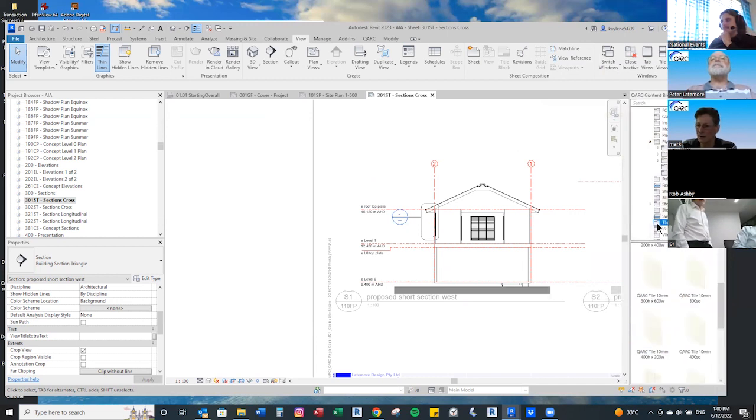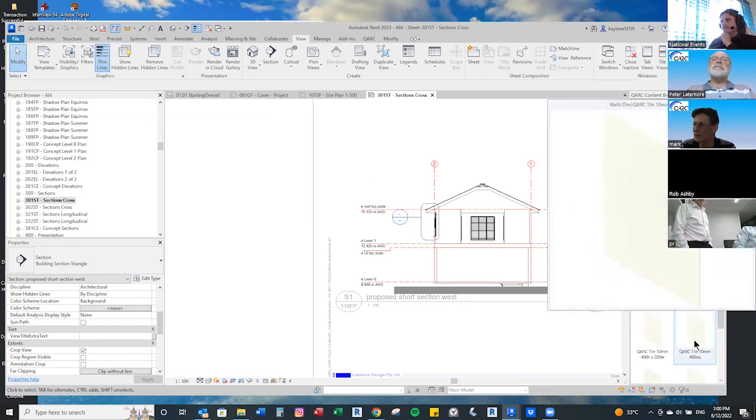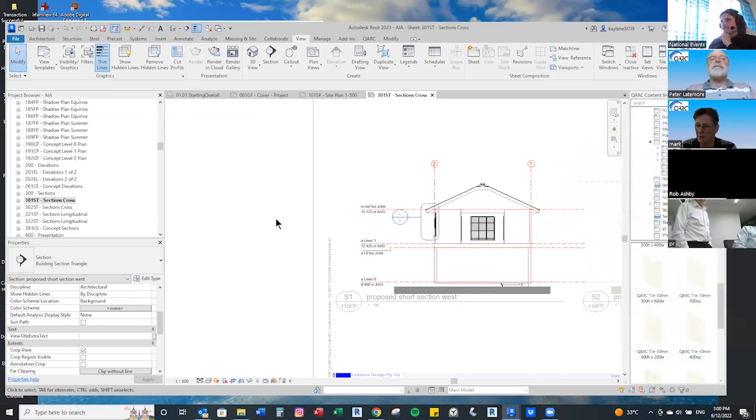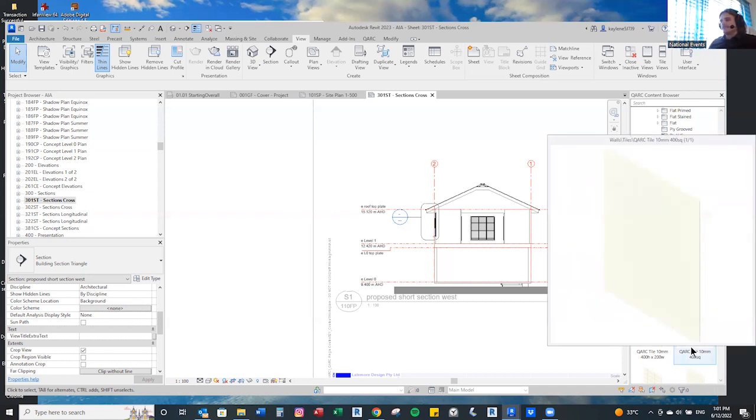Yes and no. A lot of the time we'll find that, for example, windows and doors are over-modeled. Yes, very true. We'd actually go through and pull some of the rubbish out and use what's that line thing you called? Sometimes use lines rather than actual 3D extrusions because it's just symbolic lines. Yeah, and get rid of half of them because there's just too many lines.